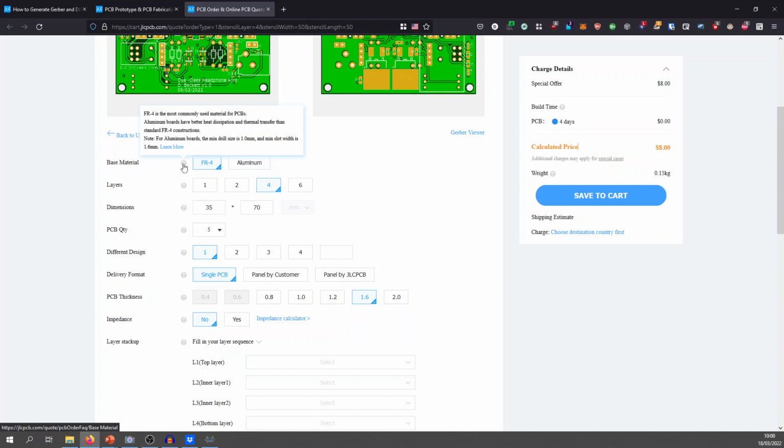So if you're doing any impedance matching traces and that kind of thing, you'd need to be very aware of what the substrate is. But aluminium boards, you find them in mains spotlights and stuff. You know, the little packages you find on the back of an LED? Yeah, because the heat dissipates. So you've got essentially a built-in heatsink. Your LEDs are soldered to these, and then that's somehow connected to the fins around the outside of it. Is it GU10 bulbs, something like that?